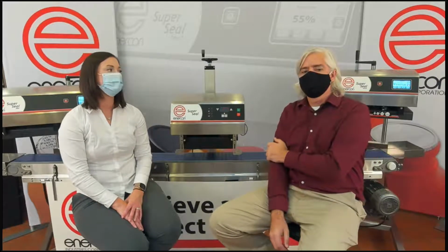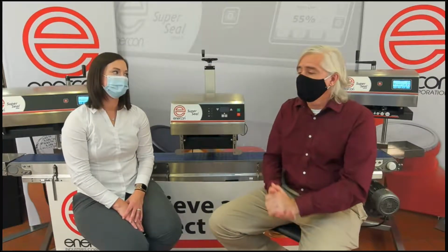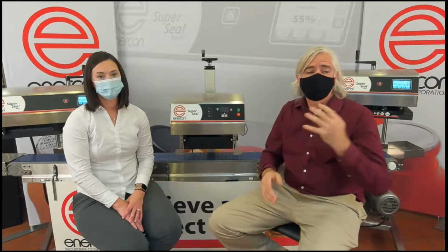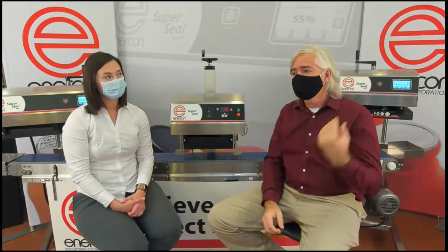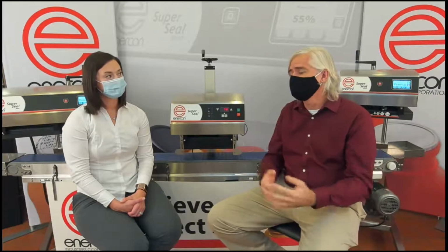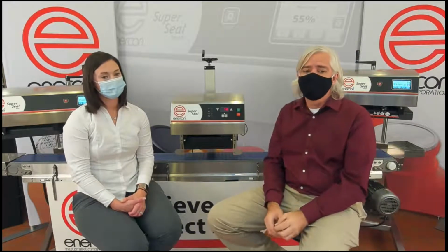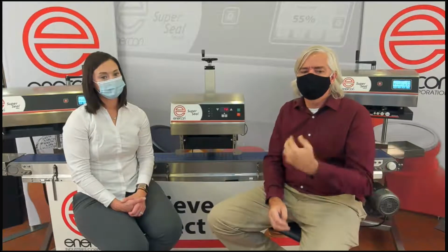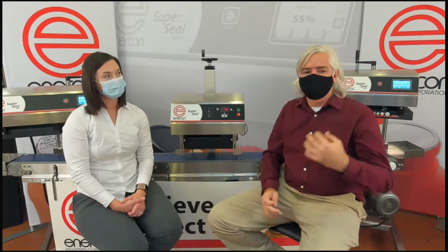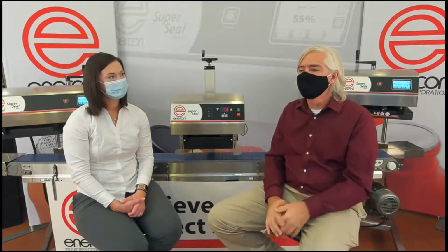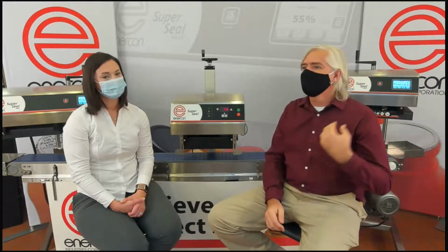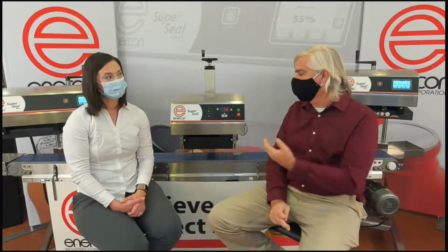And Jeff, once the sealer is positioned properly, what's the next step in creating an operating window? Well, you've got to get some containers. The best practice is to use the containers that you're going to actually be sealing and make sure that the product is in them, because the temperature is going to have an effect on the seal. You should also make sure that you're sealing products that have been capped with your capper, not by hand. You want to run at production line speed. Once you've done all that, the only thing left is the output power of the sealer.